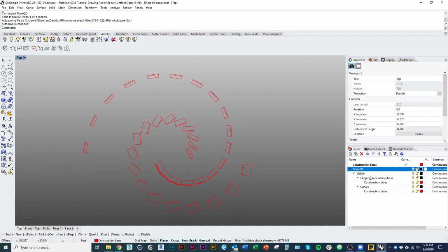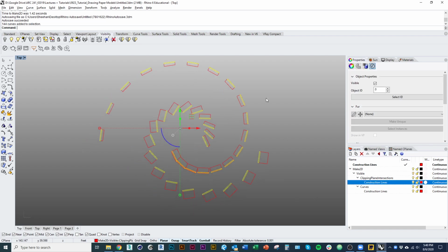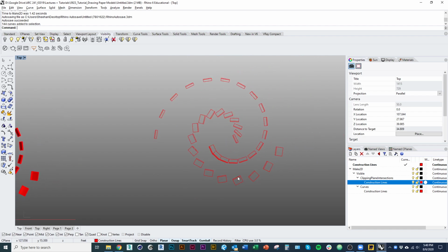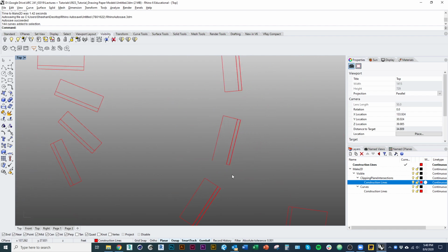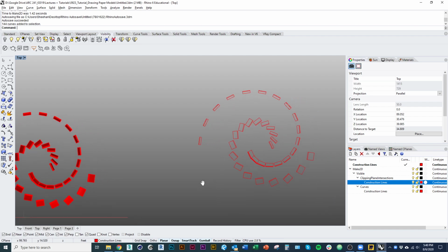For example, our clipping plane intersections, if we select those objects on that layer, you can see that it's got a separate line for every part of the strip where the clipping plane is cutting through that strip. And that's great because, like I mentioned, that'll make it easier to line weight. You will notice that on occasion, lines will be missing, like right here, for example. So Make 2D is not perfect, especially when it's looking at objects very oblique to the view.